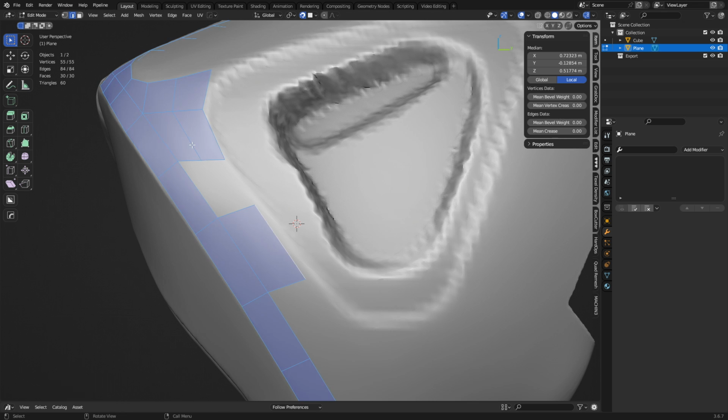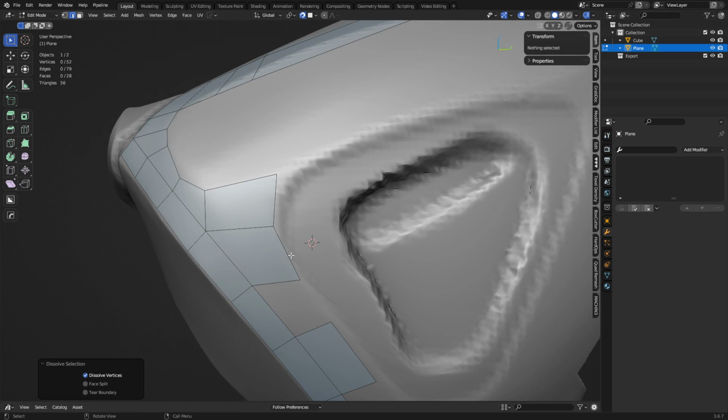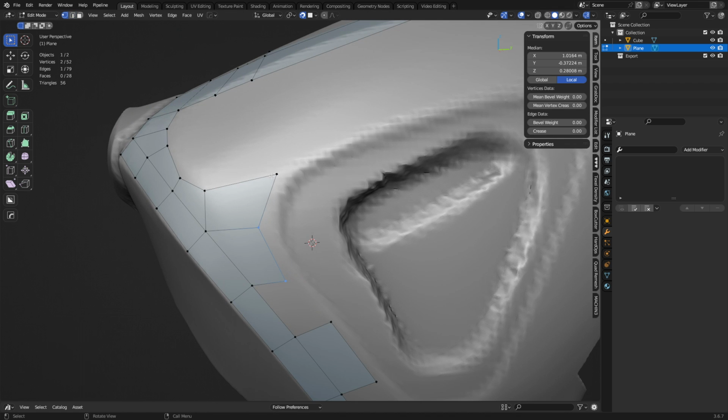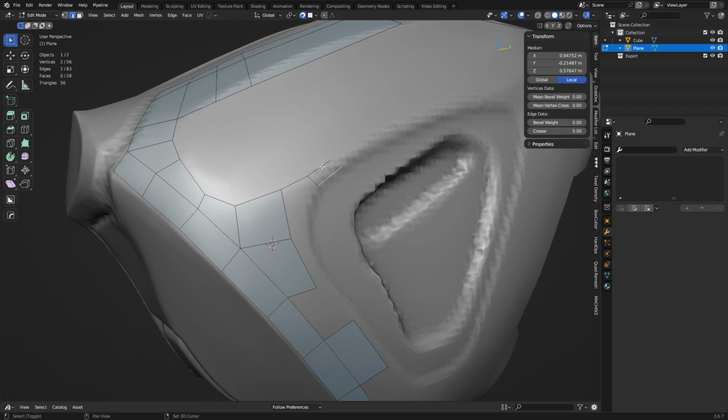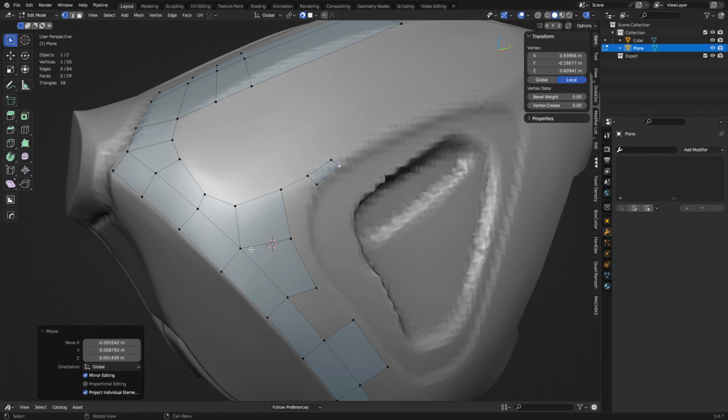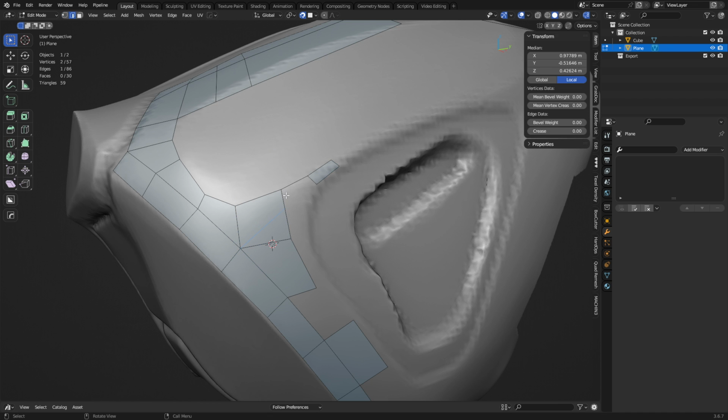I'm going to dissolve this. Might push that back a little, because this needs to stay up here. But I need an extra edge, because basically what's happening is the kind of topo we want in this area looks something like this, right? Where there's an extra face there. We don't have one over here. Could try running this through, right? And then we could use the knife tool, run it through. Maybe be able to dissolve that.